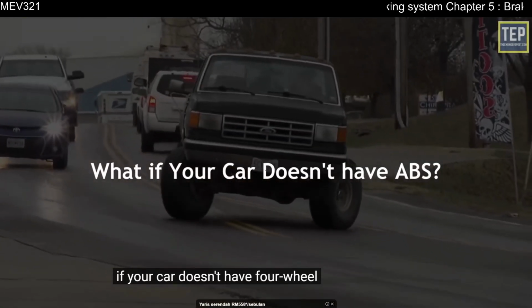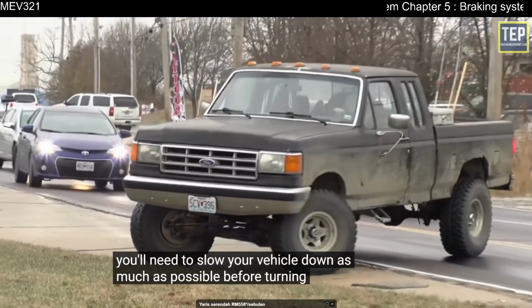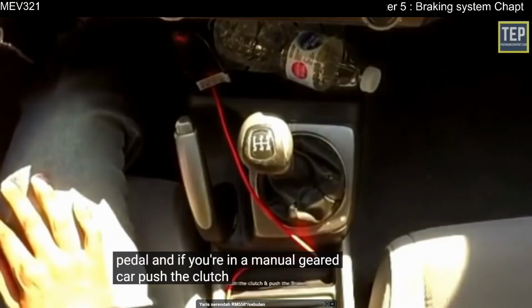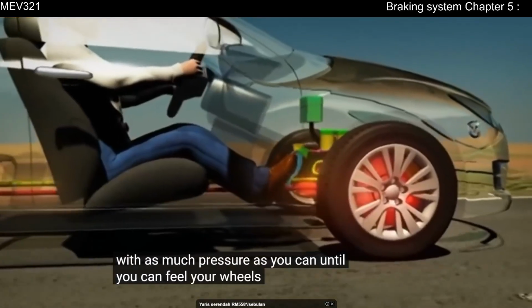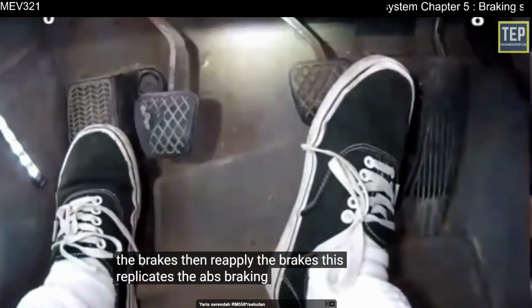If your car doesn't have four-wheel ABS or the ABS is not working, you'll need to slow your vehicle down as much as possible before turning the steering wheel. Take your foot off of the accelerator pedal, and if you're in a manual geared car, push the clutch down, push the brakes with as much pressure as you can, until you can feel your wheels lock, then release the brakes, take your foot off the brakes, then reapply the brakes. This replicates the ABS braking method.